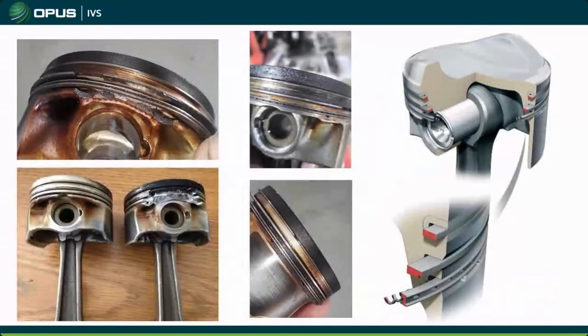So, what led to this issue that they had with pistons? Part of it is because they ran so much vacuum in the crankcase system, and in combination, they tried to use these low friction oil control rings, which you can see are not like most oil control rings. Most oil control rings are a three-piece. You have a top, then you have your spacer here, and then you have a bottom one. These are this strange I-beam system here with the spring behind it.